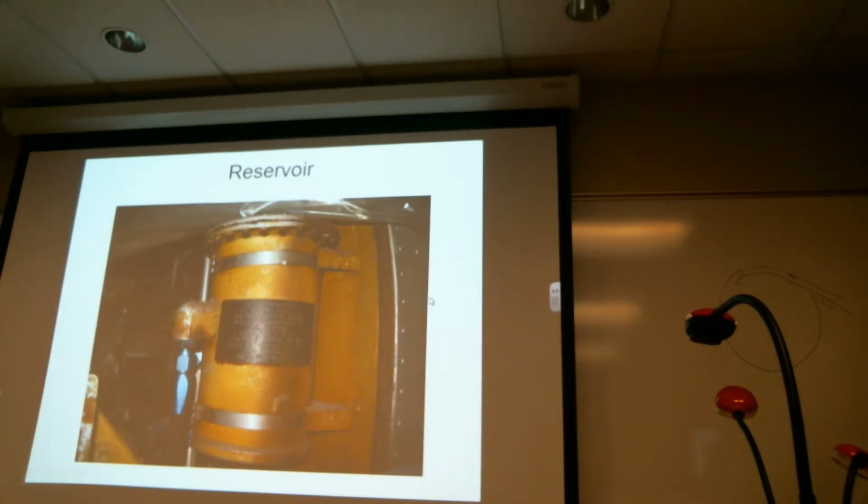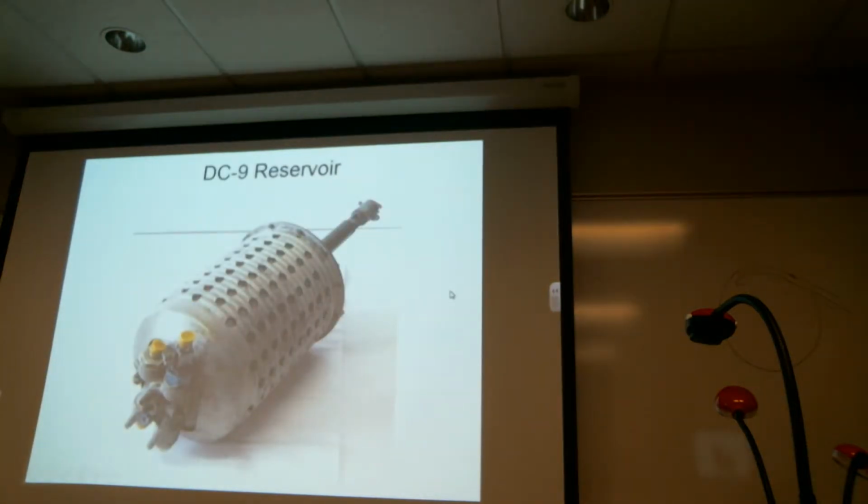Simple reservoir. This one is a pressurized reservoir. Always pay heed to the placard that's on the reservoir. You may find information that's important for servicing on it. Sometimes they'll have multiple levels that indicate full quantity. And again, full might be dependent upon actuator position. Again, you've got actuators that are unbalanced actuators. So depending upon actuator position, you may have different levels that may both indicate full as far as the reservoir is concerned.